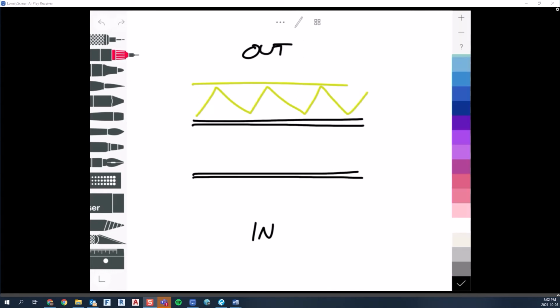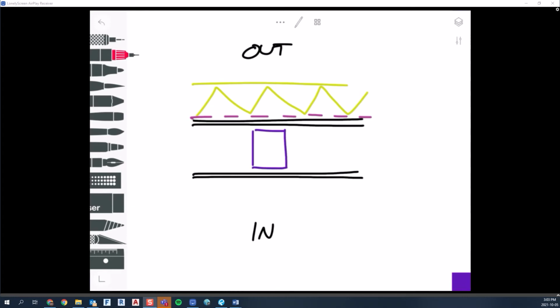Okay, and of course there'd be the air vapor moisture barrier, but again, not getting into that right now. Let's get into the systems of the relationship of the stud to the structure. So one very common approach you'll see out there is a steel column put right there, inside the stud wall. So I'll draw some studs in there now. The studs would be framed up around the steel column like so. So this is called an infill stud, where the stud work is being infilled around the column, basically.